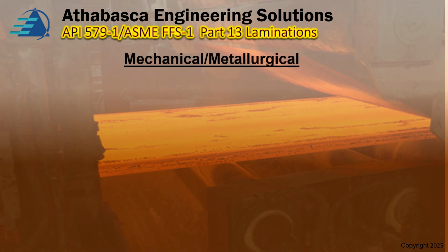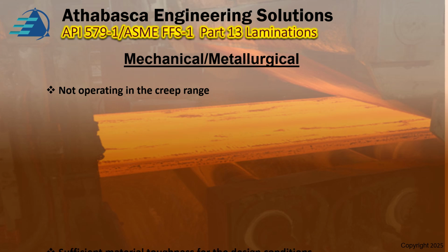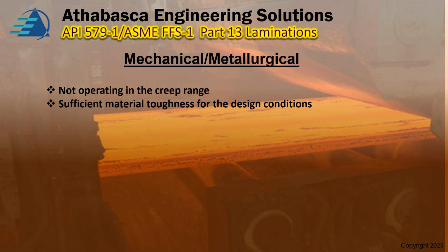Now the mechanical and metallurgical aspects of this design. We determined that the system is not in the creep range, so we don't have to revert to the part on creep for this assessment. We have sufficient material toughness for the design conditions. In all the parts, you have to initially check whether you have a brittle fracture issue or not for all the conditions, including the hydro testing.